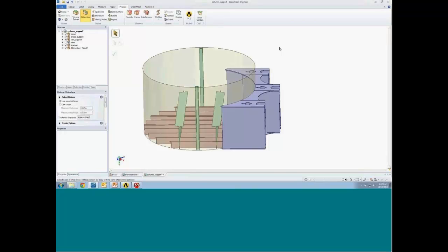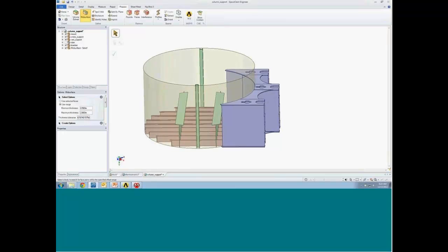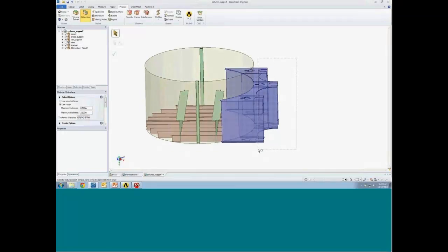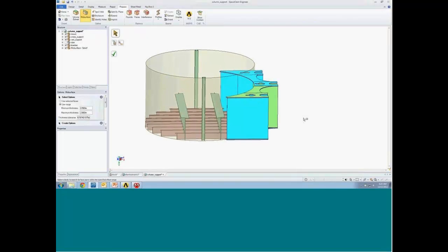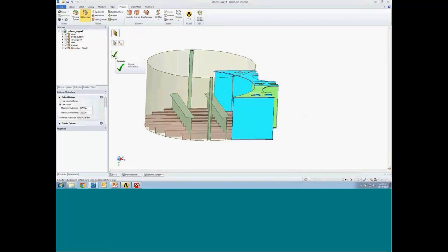Now that's just one mid-surface. Do I want to go through this whole model and do that on every thin body part? Absolutely not. That's kind of a waste of time and a poor use of tools, so we have really streamlined it and allow you to search. Well, I'll give it a search range, maybe a half an inch up to 2 inches. And I'll go through and do a big box select and tell the system essentially find all the faces that you can mid-surface. And it found quite a few there.